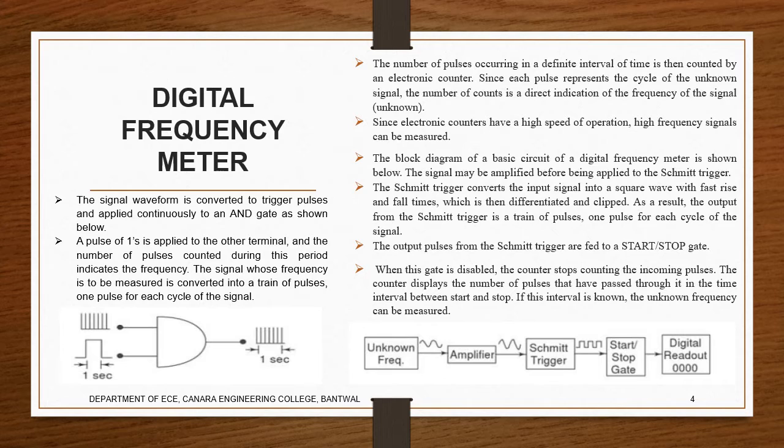So it will be converted into a train of pulses. Yes, you can see it over there. And one cycle will have n number of pulses. In the figure, you can see around 6 to 7 pulses there. So these pulses occur at a definite interval of time, and these are counted by the counters. Usually some are given to the microprocessor or anything, depending on your application.